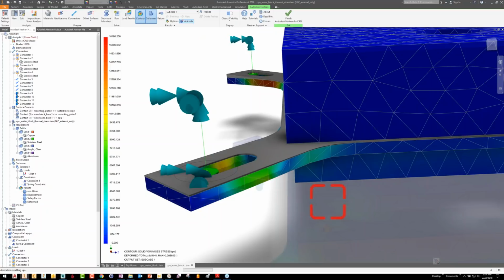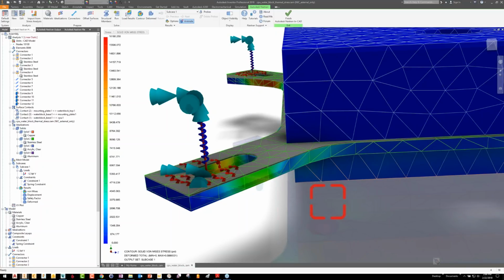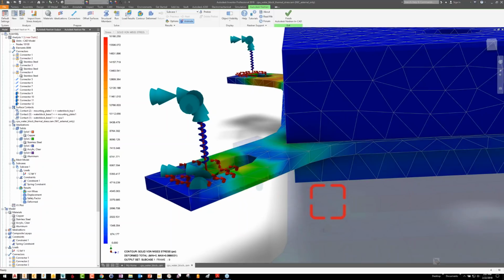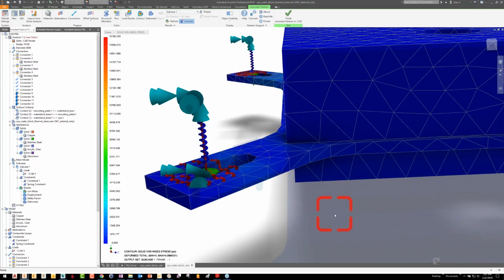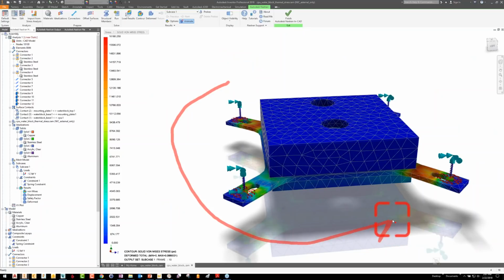So I've kind of sacrificed realistic, accurate results, quote unquote, in this area, in the name of stabilizing the model a little bit. If I hadn't held down the bottom of that spring in the other directions, think about what I had. I had all the tops of the springs stabilized so that, for instance, they couldn't rotate. And when I say rotate, I mean kind of the whole structure spinning like this, right? And those springs would just be kind of stretching and allowing that rotation. Well, in order to stop that, I really just took one point here and said, you're not allowed to rotate either. And that kind of gives it a little more stability here to prevent that tendency to rotate.